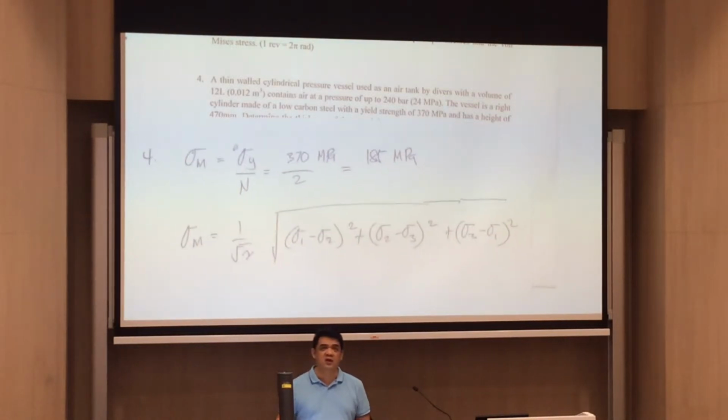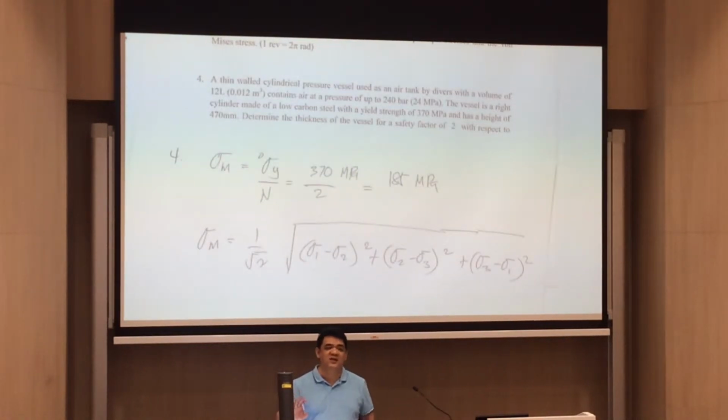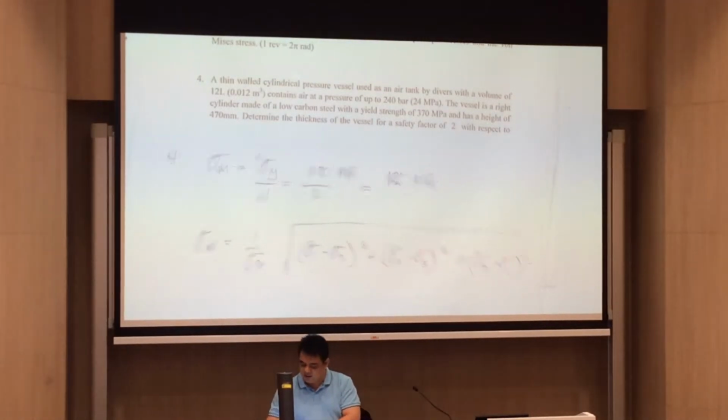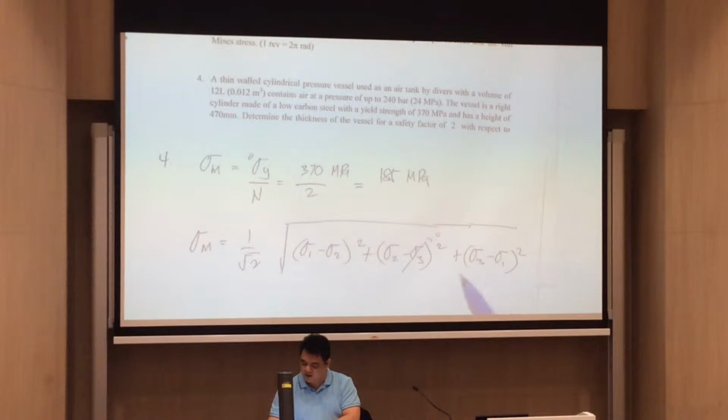There's no shear for a pressure vessel unless it's stated that you have the so-called torsion or shearing stresses. But at the moment, if we're just looking at a pure cylindrical pressure vessel with only the stress based on that internal pressure, then we're just looking at normal stresses, which are actually the principal stresses. So in this case, we don't have sigma 3. So that will be 0.